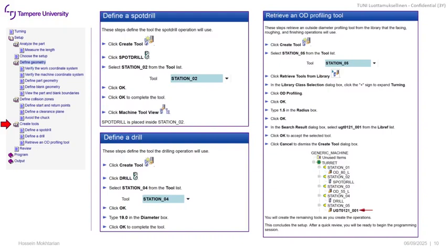You just need to make sure that you are not assigning one station number to two different tools. Of course, the software might detect it, but in case it doesn't, you will be in trouble. So first of all, each station is dedicated to only one specific tool. Second, it is preferable to use internal diameter tools on odd or even stations consistently.